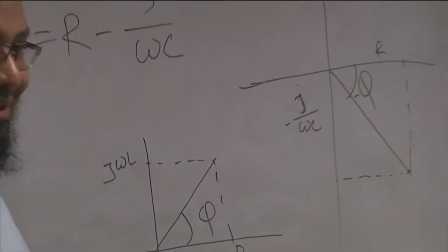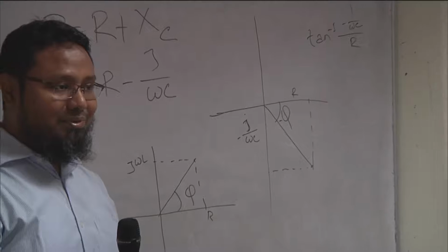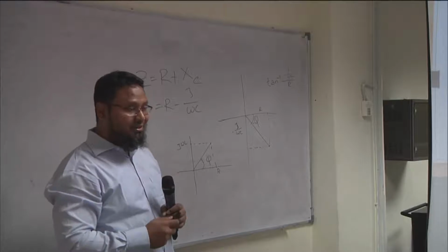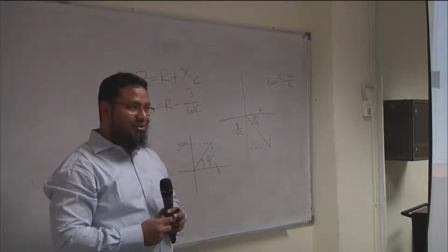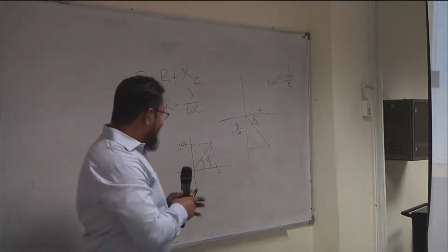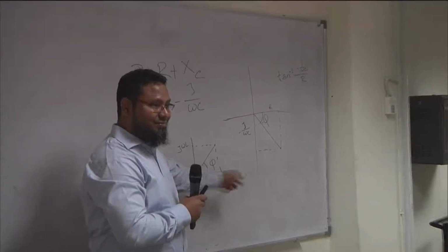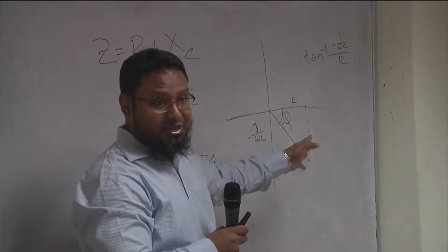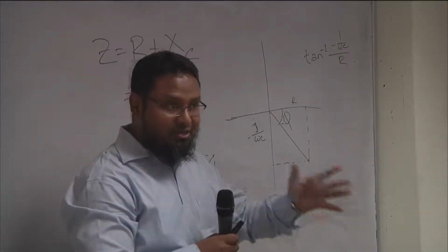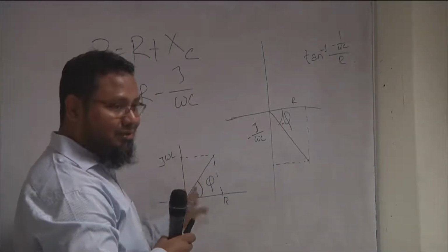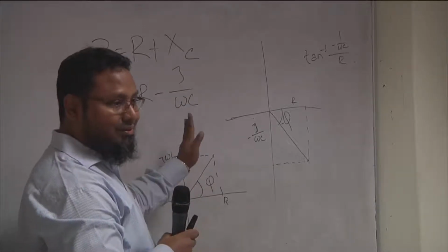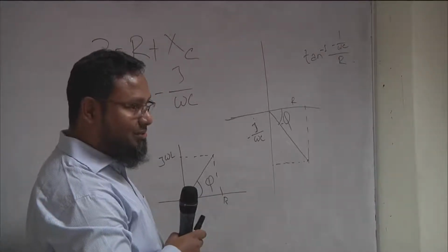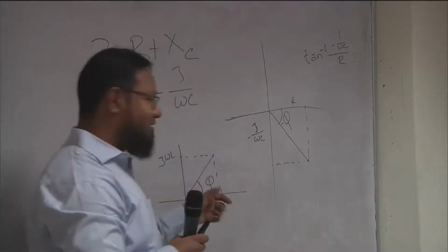Okay, I'll give you a trick question now. If we just in case have R, L, and C, all three in one series circuit, what kind of situation are you going to get? R is always in the real axis. For the case of a capacitor, you're going to have something negative. Remember, all of this behaves like a vector, right? And you add up these vectors to get the whole Z. And for the inductor, you're going to get a positive vector entirely lying along the positive y-axis. So you see what's happening here? This vector and this vector are going to cancel each other.